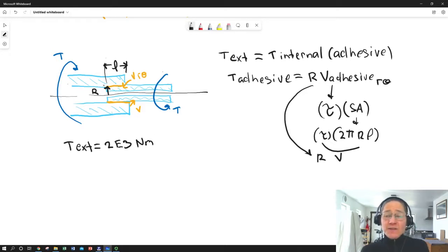So we've characterized something about the adhesive, which is pretty cool. But we don't characterize adhesives in terms of torque because it's got all of these characteristics of the test fixture. It's tau. It's the shear stress that we're going to relate to something on the adhesive and go, oh, that had a great shear stress. Let's buy more of that. Or, oh, that was too low for our application. Get a stronger one. Or if you're a material scientist, you might say let it cure a little longer and get a higher crosslink density. But regardless, we've got to use this expression to basically take away the effect of the test fixture.